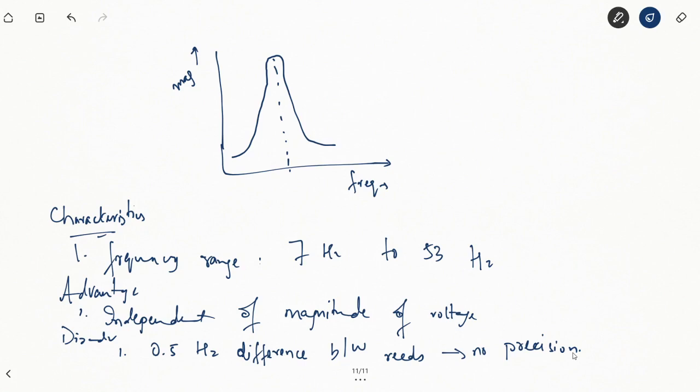So this is a simple device. You have an electromagnet that is basically an iron core around which is a winding. A voltage is applied to the winding, so that rated amount of current flows through the windings, and the current is alternating at the same frequency as that of the supply voltage.